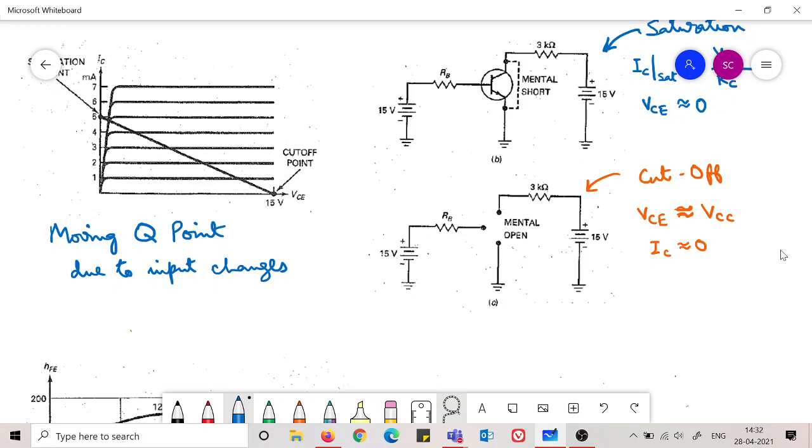The operation in the active region is current amplification. That is what we are trying to use. On the input side we give a very small current, on the output side we get a large current. This is the use of the transistor in the active region: amplification. So the amplification work is not very reliable with the common emitter configuration. You note this down in your notebooks.